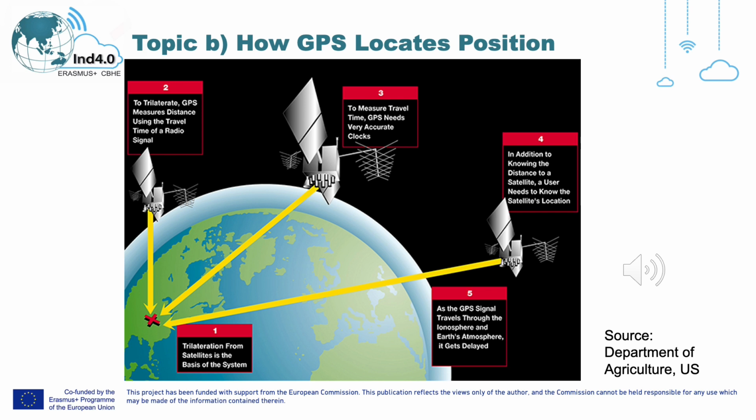Differential GPS uses a stationary monitor receiver to calculate the difference between the true position and the determination of a position from the satellites for a point in time. This allows the position of a roving receiver to have a three-dimensional accuracy of 20 centimeters or better.